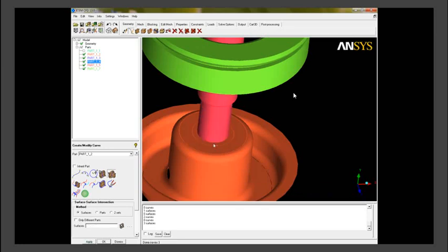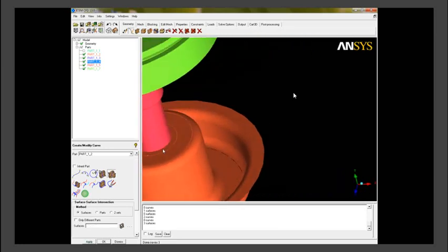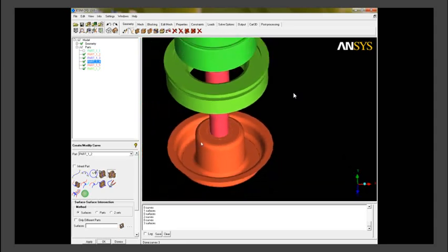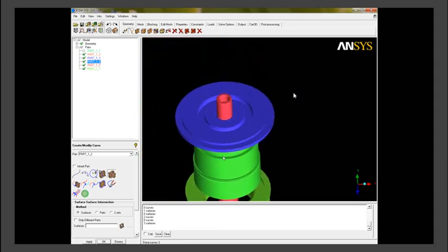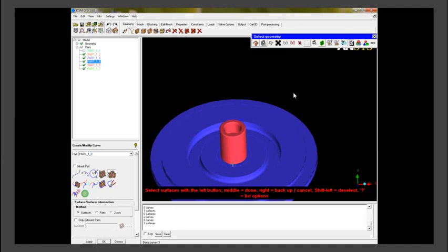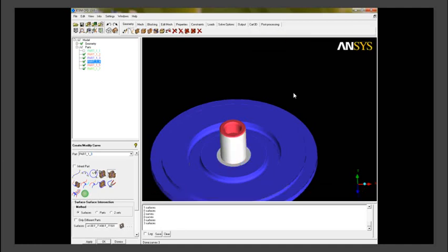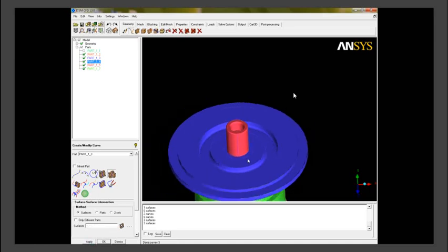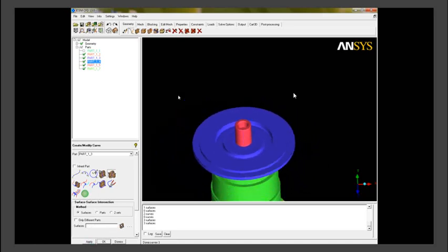In this operation, we create a curve by using the intersection of two surfaces option. What we are trying to do is create bounding curves for the internal surfaces so that we can create our own modified surfaces to extract the fluid volume. Again, we use the intersection of two surfaces option to create a new curve.